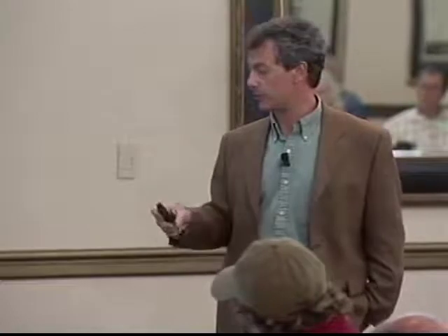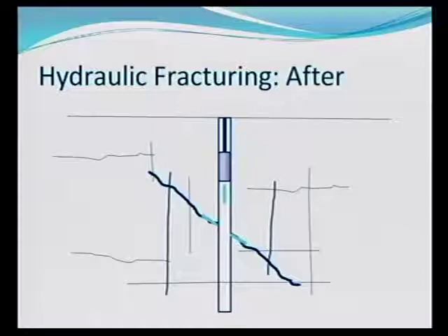So the hydraulic fracturing has been around for a while. What's kind of new is the ability to directionally drill, so you can sort of break open places that you weren't able to get to before. So the general idea is you're going to increase the pressure here, force fluid in there, and open these up. In the oil field, they use proppants to keep the fractures open once they're open. But the general idea is you want to increase the permeability. And this allows you to extract more fluids than you would be able to extract in the natural formation. So this is used in conjunction with some of the other techniques that I'll show you, and I'll point that out.